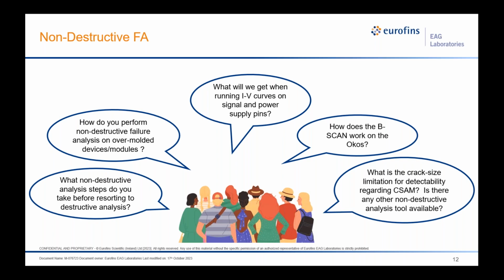The concern with B-scans is that you lose part of your signal at each interface. At each interface, some of your signal gets reflected and some gets transmitted. If you hit an interface that either absorbs or scatters your waveform, you basically lose some data for everything below those interfaces, and so the B-scan will get impacted. It's kind of like a pseudo 3D image based on just a top-down optical image. You get those curtaining effects where your line of sight is broken, so it's a similar kind of problem with B-scans.